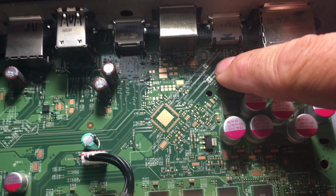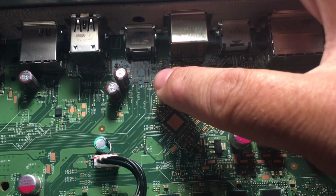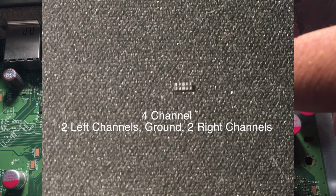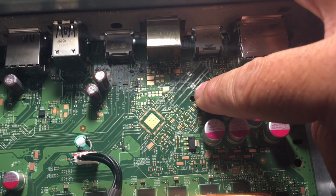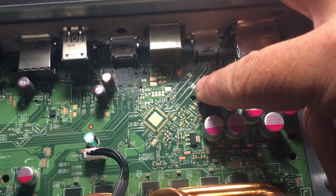And Andrew Paul shows you how you can test this. Basically, you can do a continuity test. They are considered 4-channel filters. There are 2 channels on the other side and then ground in the center. So essentially there are 10 pins. This is actually a straight through connection. So the ESD filter just sits on the line.